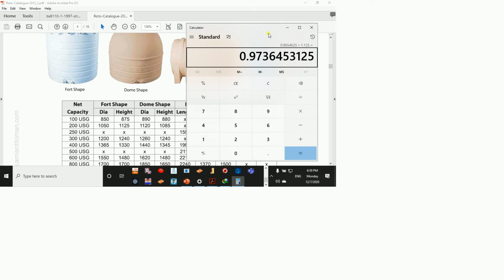They have the concept that eventually the load of the water tank will go to the beams, and that's correct. But you are ignoring another thing, that this slab is going to deflect a lot because of having a huge load in a certain area. Now you are assuming that it's distributed along a bigger area. So rather than having 8 kilonewton per meter square, your load tends to be 3 kilonewton per meter square because you are distributing it over a larger area. And that's why in some cases the rooftop will fail. So that depends anyhow on your engineering consultancy and how they are doing things.